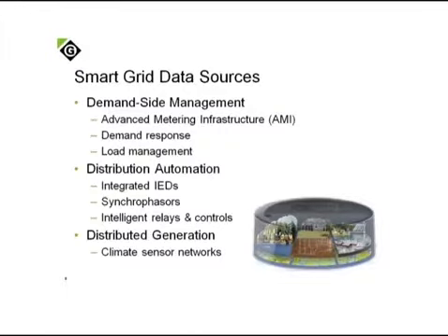And again, the distributed generation, some of the challenges there. It's great that we're seeing a lot more rooftop solar or wind generation, but the problem is that there are clouds in the sky, and when clouds obscure photovoltaic cells, voltage goes down, output goes down. So by marrying climate information, we understand that there are clouds in the sky and we know what direction they're moving in. If we know where our photovoltaic cells are, rooftop solar is, we can now understand and model, if we have that sensor information, where that peak demand and that peak power is going to be as it rolls across the network. So we can proactively plan for and react to those types of power variations.